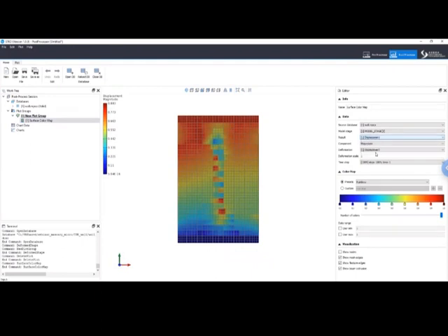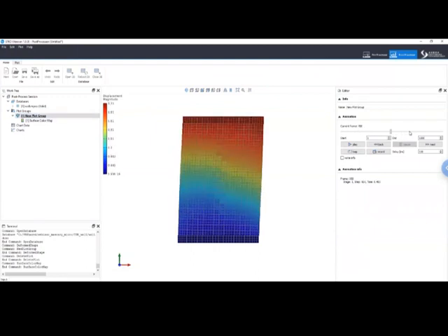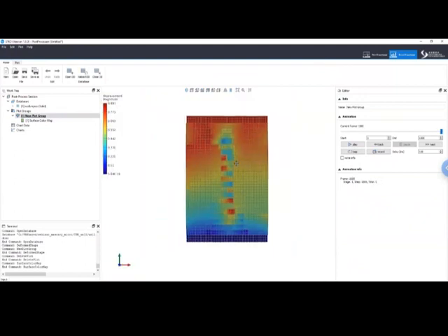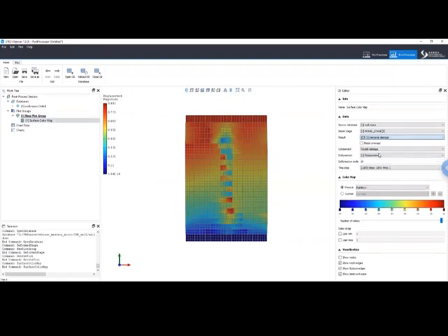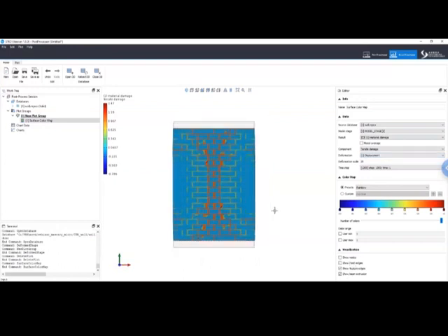So let's see first the displacement. Let's make a deformation scale of 10, or actually 20 should be fine. And let's try to do an animation to see what happens. So this is what is happening. From the displacement, you can see the displacement jump here. So you can see the formation of the crack actually. Okay. But probably it is better to visualize other results. So this one is the displacement. You can go here, you can change. For example, some significant results can be material damage. The material damage is actually, let me switch off the mesh edges so the, okay, this output will be better.